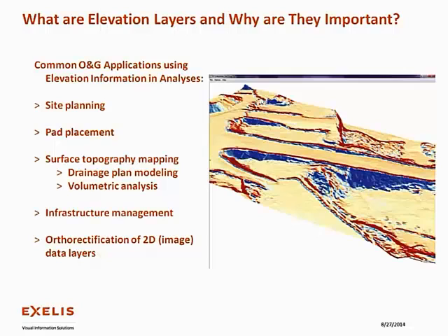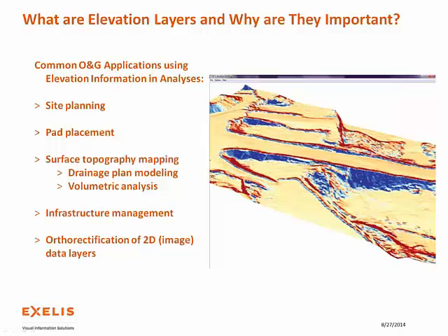So some people find remote sensing ways to derive surfaces are actually a little bit more useful than ground surveys in some cases. Volumetric analysis is also something significant that we see our customers do. So surface rendering can be used to compute volumes and even to monitor surface changes over time to indicate where maybe a wellhead backflow pit might undergo a change, or monitor smaller, large-scale land subsidence that needs to be addressed for safety operations. There's a lot of different reasons to use DEMs and surface information. They're important in a lot of analyses across the board, from operations and planning to mitigation and safety.